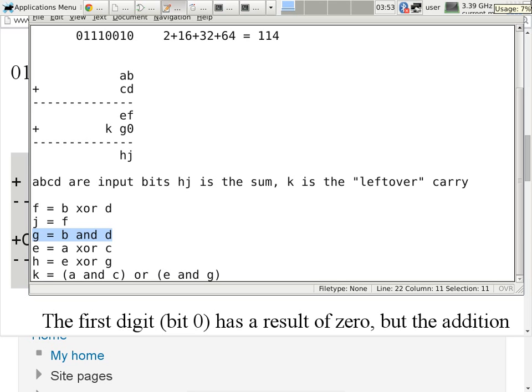So it's sort of particular to our example. Just a quick question. So within the red box, it's called a half adder? No, the whole red box is a full adder, consisting of 2 half adders and then an OR gate. So when you say a 16-bit adder, or a 4x4 adder, do you mean 4 4-bit numbers to be added together, or you're adding 2 16-bit numbers?